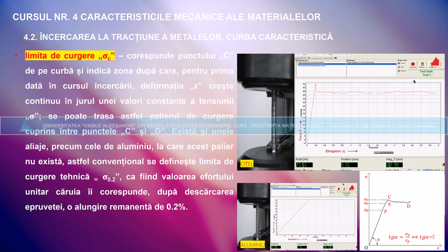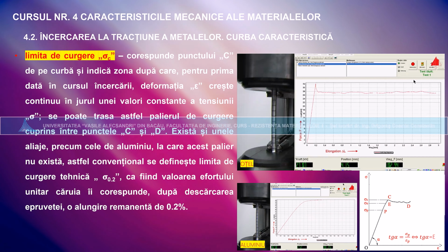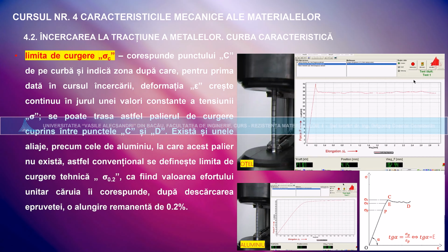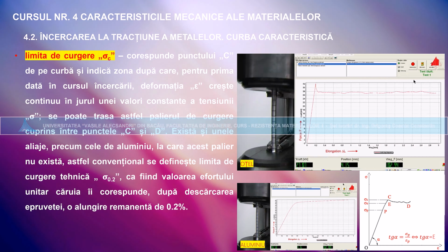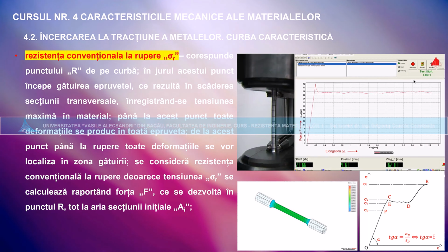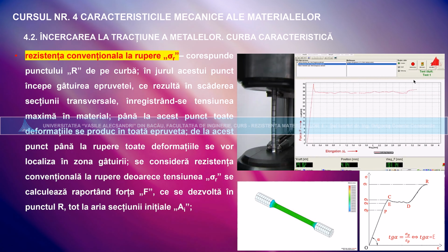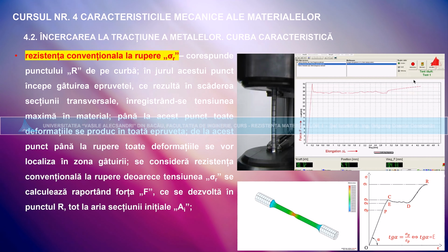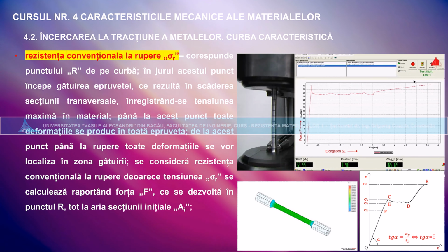But this time, the end of the elastic area is not revealed by a sudden drop of force or any distinct change. There is a smooth and gradual transition from linear elastic behavior to plastic deformation. After a certain strain, known as the Luder strain, the force increases again. The material opposes an increasing force against the imposed elongation. It strain hardens.